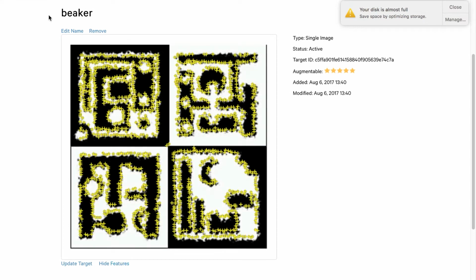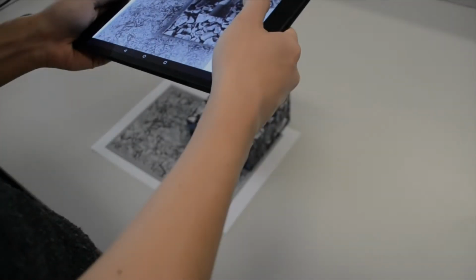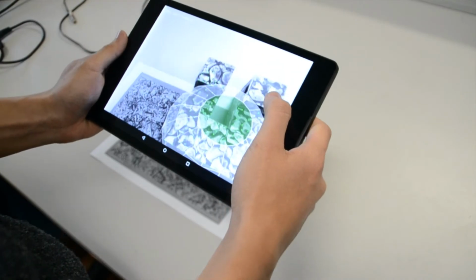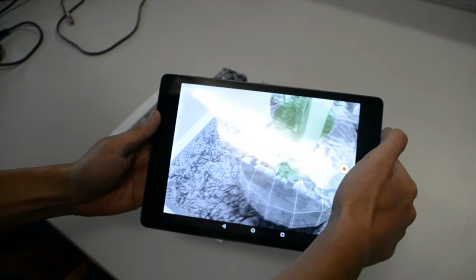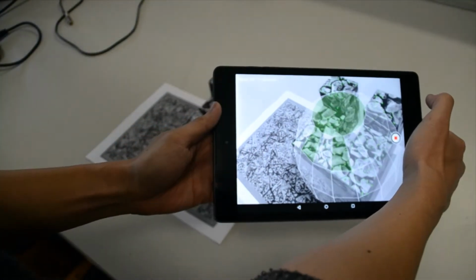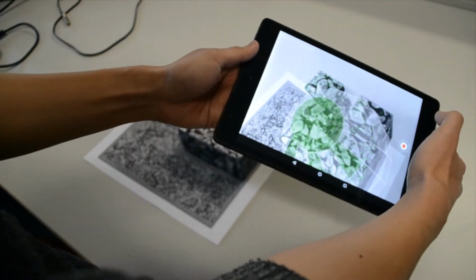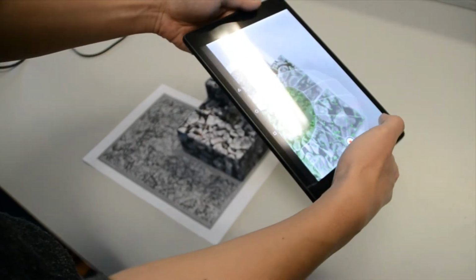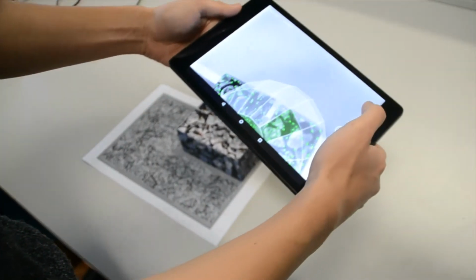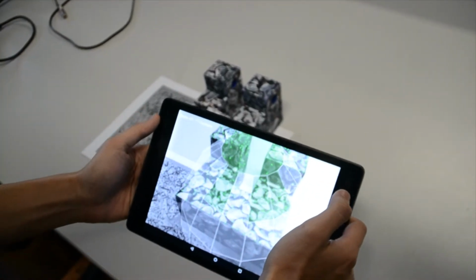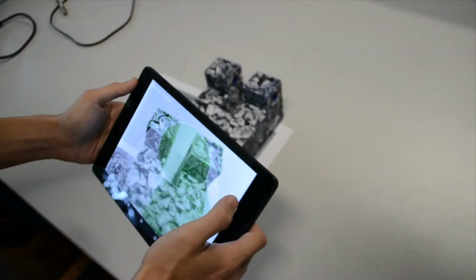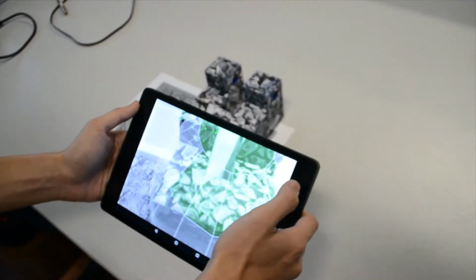portal, where the subsequent feature points on the marker will be extracted and then exported to the library for the tracking mechanism. As for the 3D object target tracking, the object needs to be placed onto the specific target marker, where the feature points of the object can be extracted with the Vuforia object scanner that is installed onto the mobile device. Objects should be scanned under moderately bright and diffuse lighting. To the extent possible, the surface of the object should be evenly lit and not contain shadows caused by other objects or people.